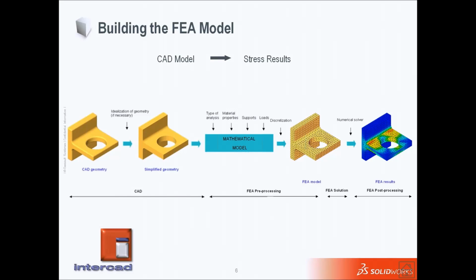Therefore, we can do the simplification, but this fillet, where we are expecting a lot of stress concentration, will remain there as one of the main features. Therefore, the first step is the design, and then doing a right simplification to our CAD geometries.